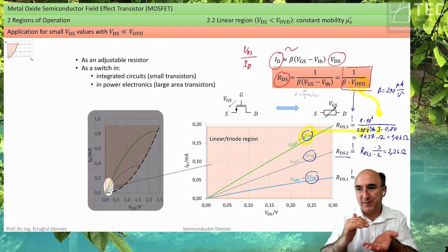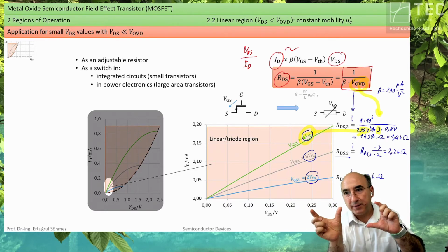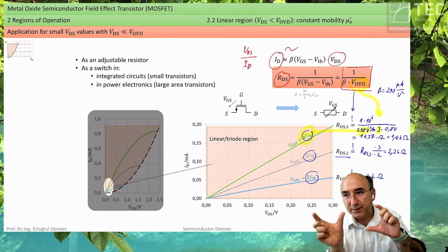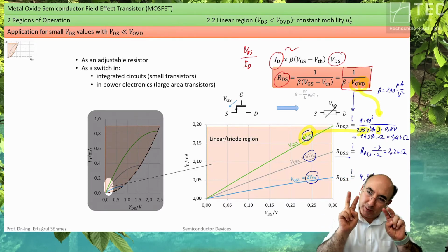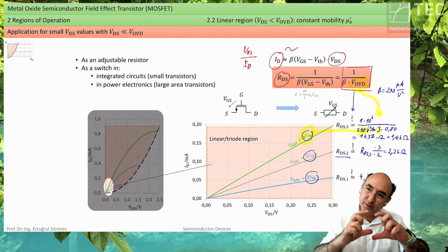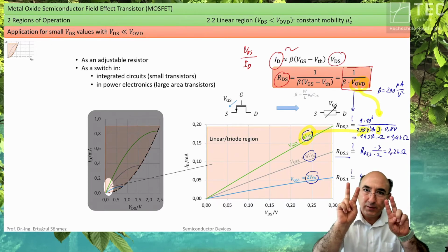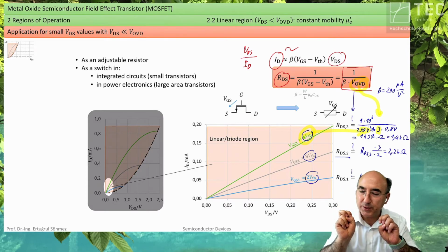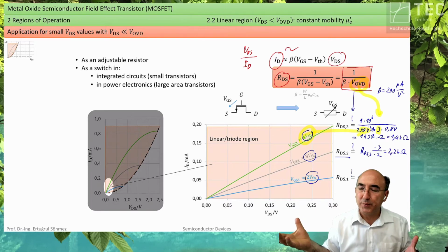And this means you have a voltage, you have a current. What do you have? A resistance. You can set virtually the resistance of a circuit by changing its frequency. And you can set these virtual resistors to very large resistance values.